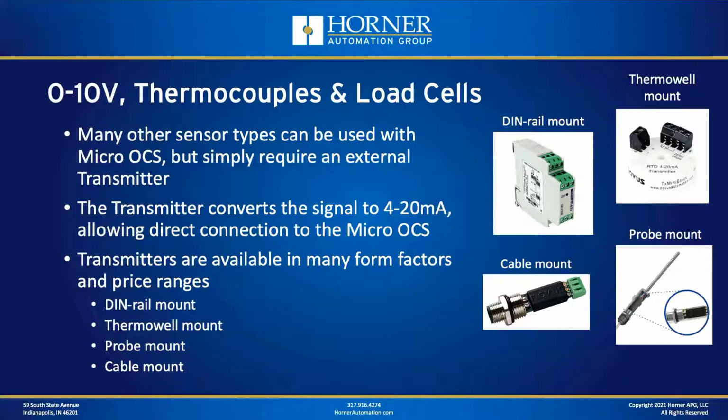They've got a really nice selection, but that's just one company, a company that we like and have worked with for many years. You can get transmitters from a whole bunch of different companies, again available in a wide variety of shapes and sizes. And really, anything outside of 4 to 20 milliamps or anything outside of RTD from -50 to +200C, you pretty much need to use a transmitter for that conversion.